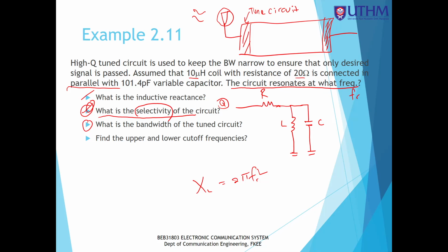Let's say that ideally the antenna receives frequencies from 57x kilohertz, the entire AM bandwidth, for example from 57x until 17xx kilohertz. So the tuned circuit will limit the frequency band.